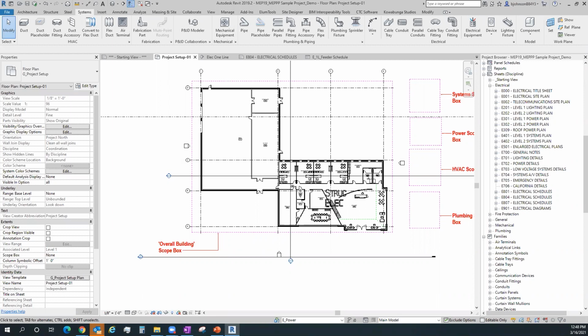So it lets you use the real equipment in the drawing and place a real OneLine that's done in an actual drafting view. So it's not using a OneLine design option like we have here. It's using a real drafting view, but somehow it's coordinating the equipment with the real symbol inside the project. So if you delete the electrical equipment, it should remove the symbol as well. So that's another option that's on the low end for cost, to have an additional methodology to do electrical OneLines in Revit. It also does short circuit and arc flash, if I remember correctly.